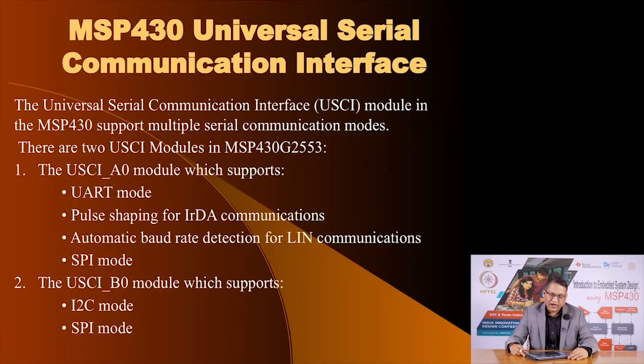Now, let us look at the serial communication capabilities within MSP430 in the context of these 3 protocols, and we will see how the serial communication peripheral on MSP430 allows you to select one of these 3 protocols. There are 2 serial communication interface modules in the MSP430 G2553 that we are using, and they are called universal serial communication interface.